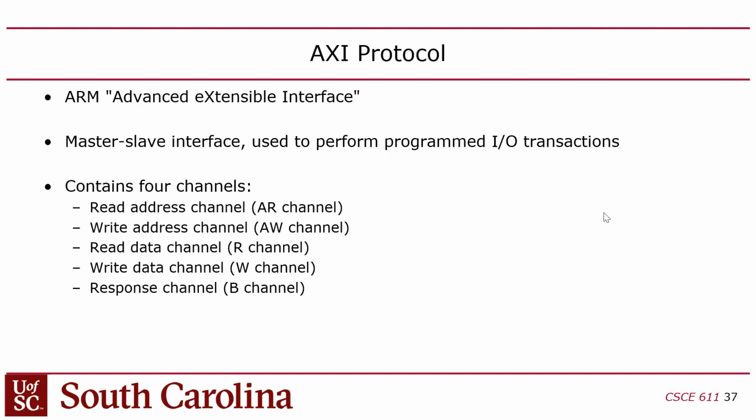So it's not a simple thing where you send an address out and read, and then you wait for the response to come back. You don't want to have to wait for the response to come back because that's going to lower your utilization, right? You want it to be more flexible. So the way they solve this is the bus actually has 5 different channels in it. There is a read address channel, a write address channel, read data channel, write data channel, and a response channel.